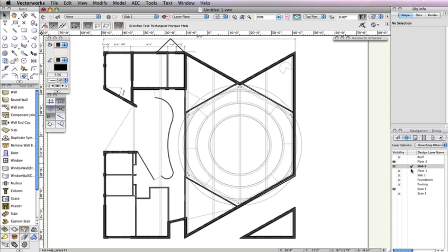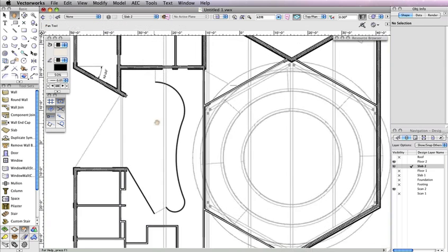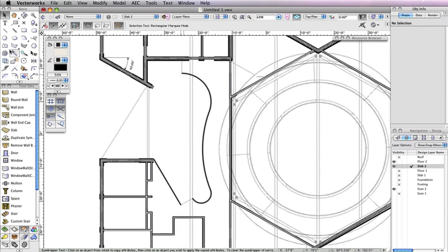There's only a small section that doesn't have existing geometry to reference, and that's this area, which is actually a balcony with the handrail. So let's start by drawing the handrail shape first. To create this curved handrail shape, you'll need to use the Polyline tool in Point on Arc mode. Select this tool from the basic tool palette, and also select the correct mode in the toolbar.